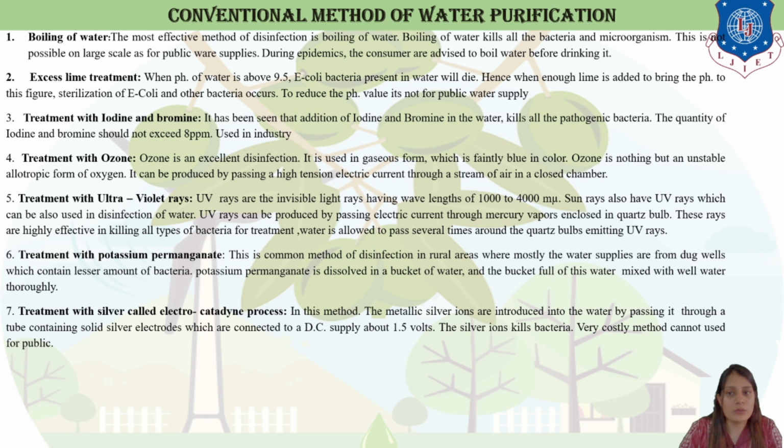Treatment with ozone, which is in gaseous form. Yes, you have seen that an oxidation and reduction process takes place. Basically, ozone is nothing but the unstable allotropic form of oxygen, produced by passing a high tension electric current through a stream of air in a closed chamber. It will clear the bacteria from the water.